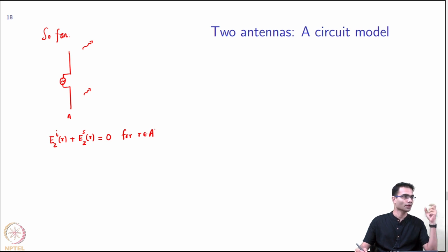It will change. So the input impedance that you have calculated for a single antenna in free space, you are very happy about it, you put it into an electromagnetic environment where there are various objects and suddenly you find that your performance is not so good. One major reason is that the environment around has changed, so the input impedance of the antenna has changed, and therefore the matching condition is no longer valid.